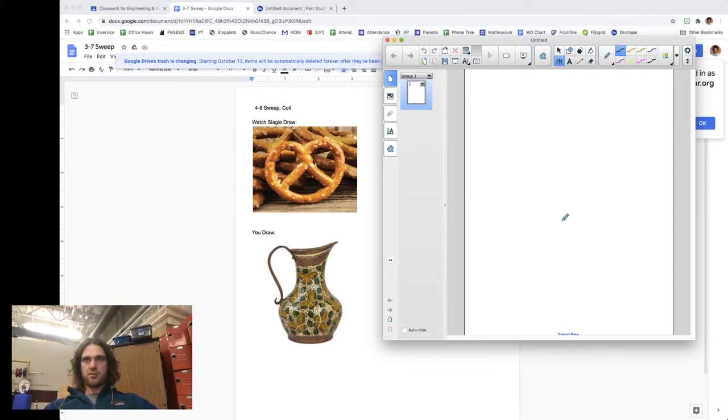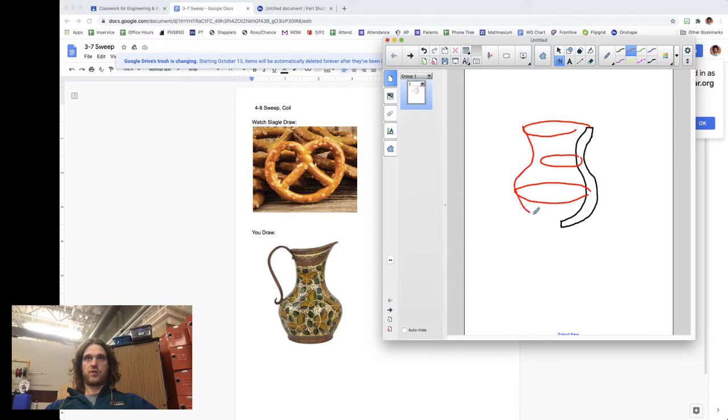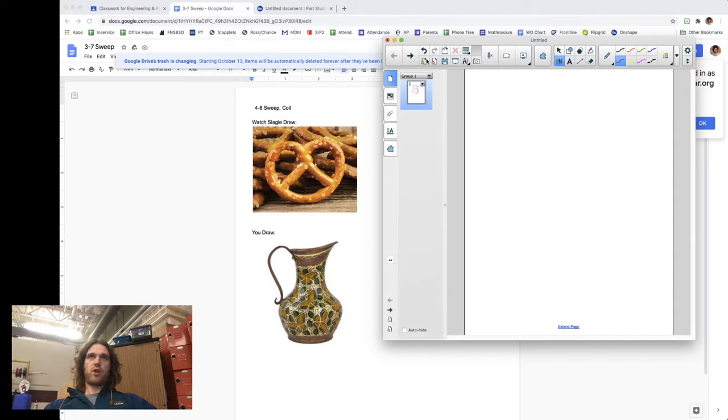So the best method for drawing this picture is first you create the thing that you're going to revolve, and it needs to have a thickness. So you're going to create a shape like this. You're going to grab the revolve tool and spin it. It's going to create this full-size picture, but you'll notice the top of that picture is going to be straight across, and that's a problem.